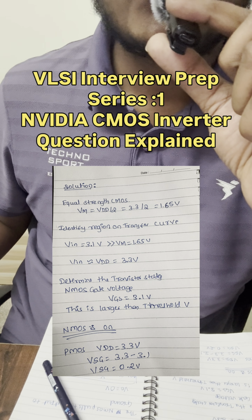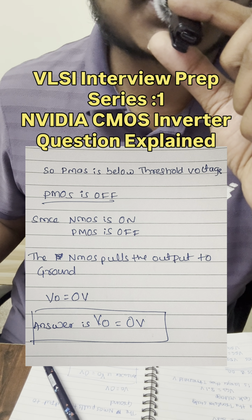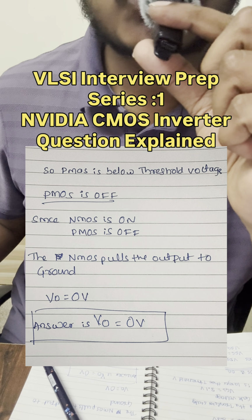When the input voltage is high, the NMOS transistor receives a large gate voltage and turns on, while the PMOS transistor sees only a very small gate to source voltage, which is not enough to turn it on. So PMOS remains off.